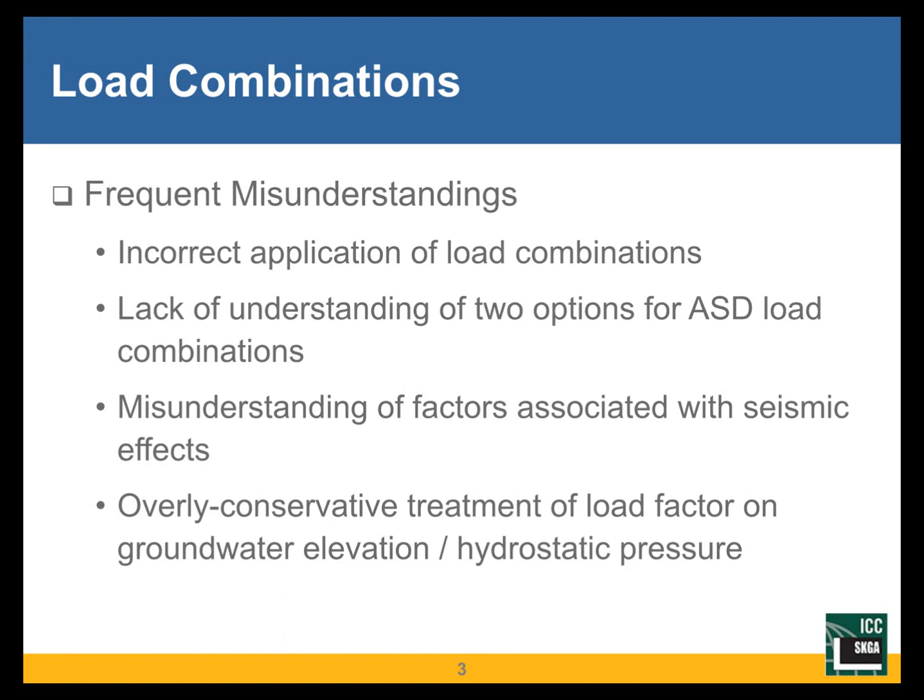So the most frequent misunderstandings that we see in load combinations in the foundation world is just incorrect understanding of how they are applied to foundations. There's numerous exceptions and special conditions that you need to consider that are unique to foundations. There's also some confusion since there's actually two options for allowable stress design load combinations in IBC, and most people aren't clear on when to use which of these. There's also frequent misunderstanding about factors associated with seismic effects and how those are applied to foundations. And then finally, we'll close out the discussion with evaluation of groundwater elevation and hydrostatic pressure, because simple application of code without thinking about it too much will lead to a very overly conservative treatment of these conditions, depending on your project.